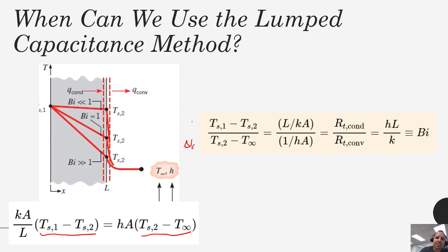I want to emphasize that the thermal resistance method still does not apply if you want to quantify the flow of heat. You can't use that method. You can't quantify the flow of heat using the thermal resistance method when you have a transient system, because remember, a lot of that heat is being absorbed by the system as you go along. However, doing this steady state analysis to figure out the Biot number tells us a lot about how we could more effectively solve that transient problem.